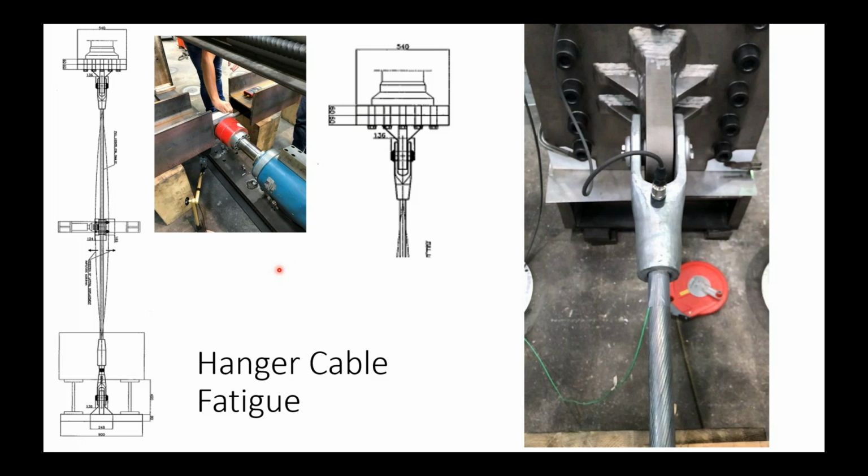They did their own construction engineering, and as I mentioned, they came up with a different erection scheme where they built the entire deck high, and then once they got all the stays connected, they lowered the false work, and that put the additional load into the system. But there was definitely a lot of interaction between our team and the construction engineering team.